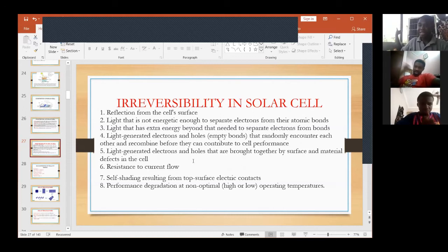So this panel is about 1 square meter. Mr. Ben, you are with us from the beginning of this class. We said the solar constant is 1000 watts per meter square. Sure? What does that mean? That this panel should give us 1000 watts. If we know simple mathematics, is it not true? But conversely, it is giving us 100 watts. That shows that it is 10% efficiency.